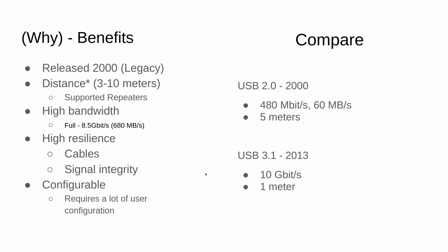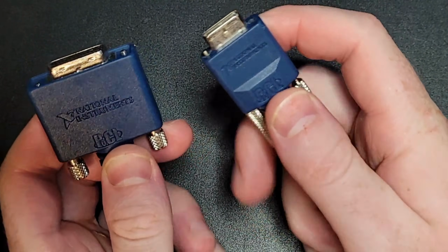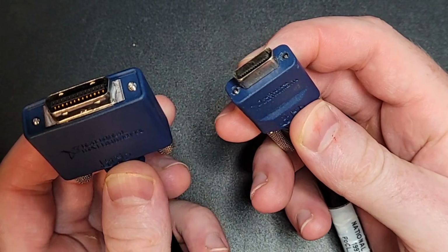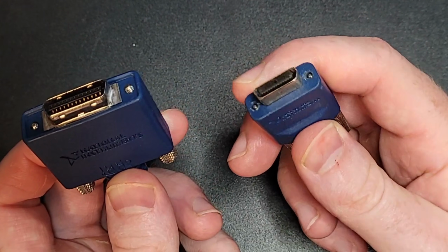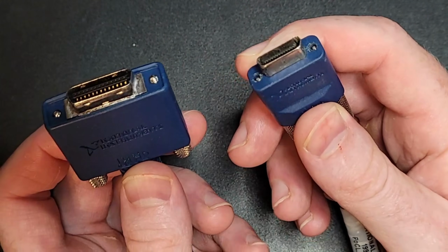All right, so now I'll show you some Camera Link equipment, and we'll go from there. All right, let's move that over. So I've got a Camera Link connector here. We have the MDR and SDR, and this is one specific cable. It's very common for your camera potentially to have an MDR, but most frame grabbers use the SDR because it slots better into your PCI cards.